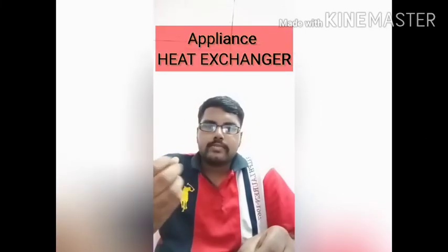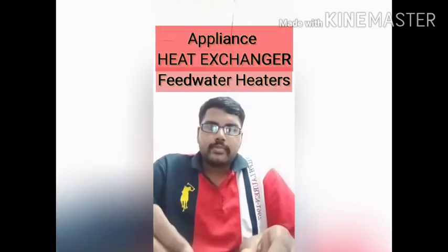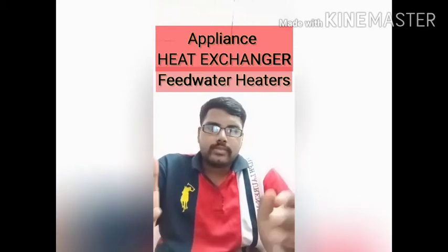So now I will explain about the application of heat transfer in industry. The thing that I'm going to touch on today is feed water heaters. Feed water heaters are heat exchangers. They're designed to preheat boiler feed water by means of condensing the steam extracted from a steam turbine. I will show a brief picture of the components of the feed water heater.